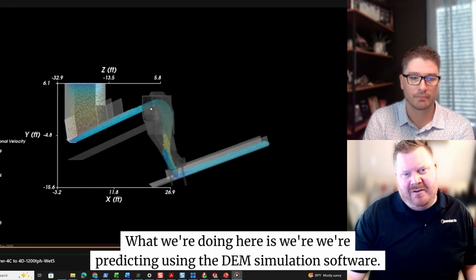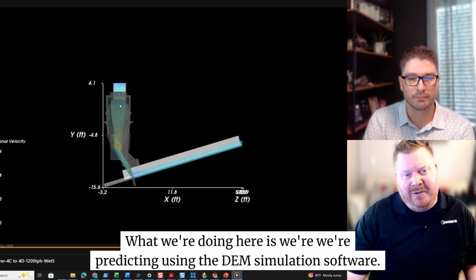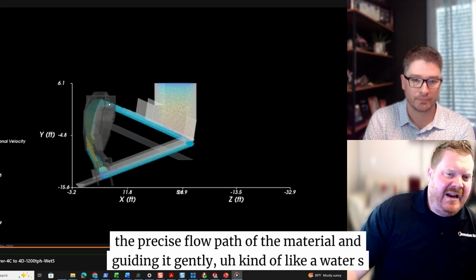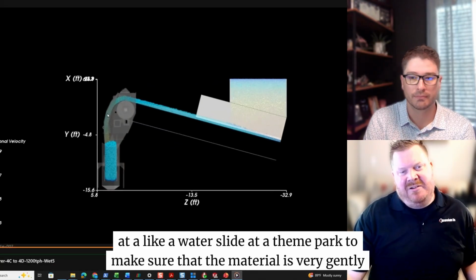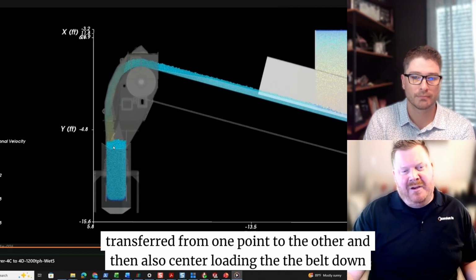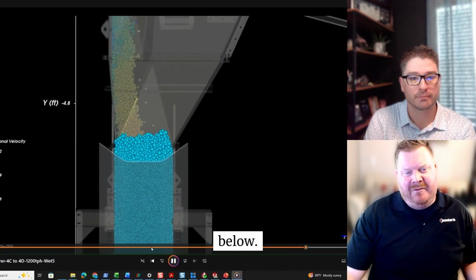What we're doing here is we're predicting, using the DEM simulation software, the precise flow path of the material and guiding it gently, kind of like a water slide at a theme park, to make sure that the material is very gently transferred from one point to the other, and then also center loading the belt down below.